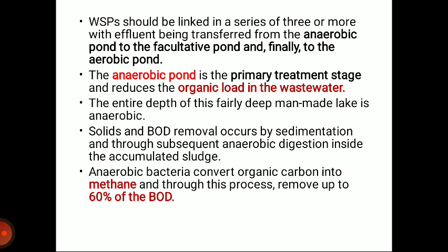WSPs should be linked in a series of three or more, with the effluent being transferred from the anaerobic pond to the facultative pond, and finally to the aerobic pond. The anaerobic pond is the primary treatment stage and reduces the organic load in the wastewater.